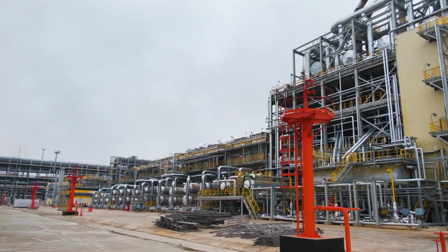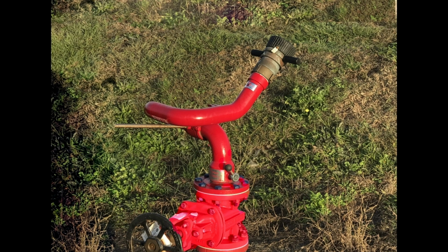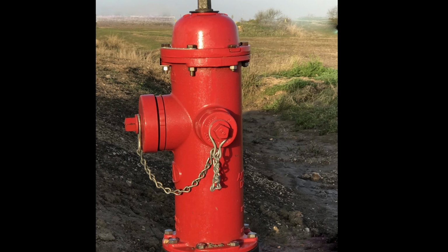Also, as an example, take a dry film thickness reading of a fire hydrant or a PIV and compare it to the dry film thickness of a project pipe paint. And then also, just for humor, compare the dry film thickness reading of the fire hydrant to your work vehicle paint thickness. You'll notice that the paint thickness of the fire hydrant or PIV is closer to the vehicle dry film thickness than it is to any of the project pipes.